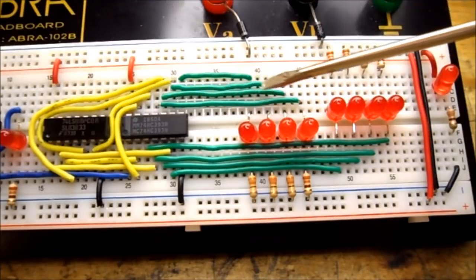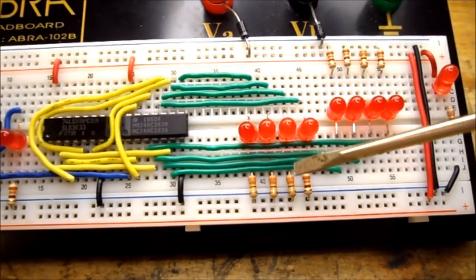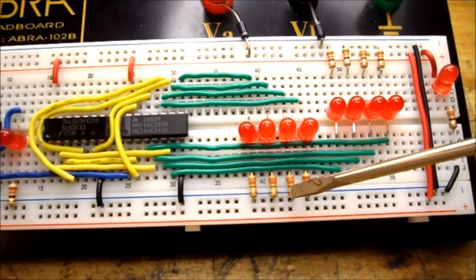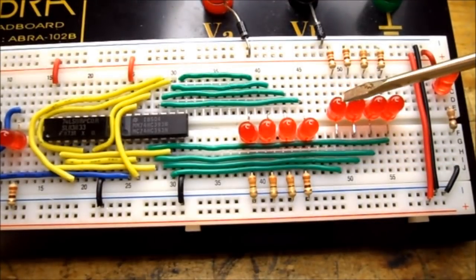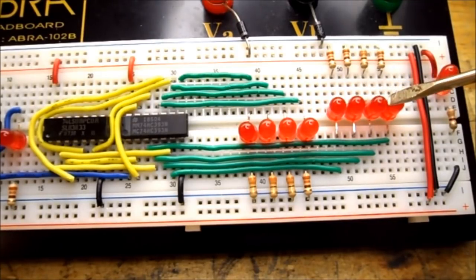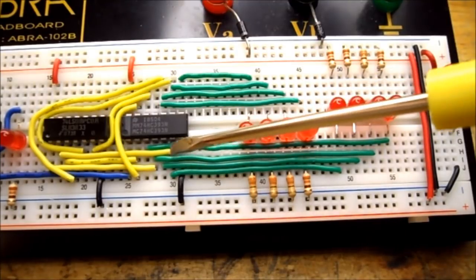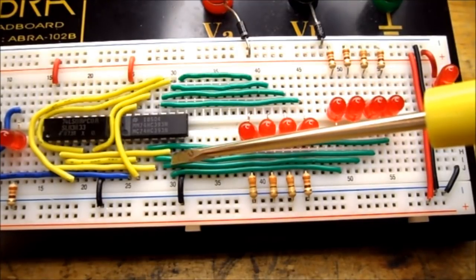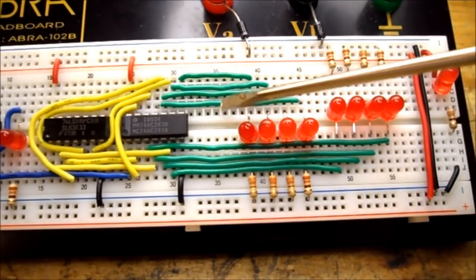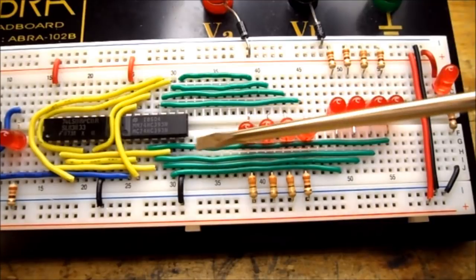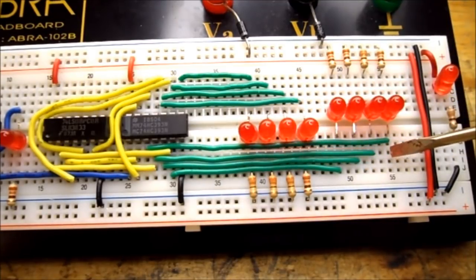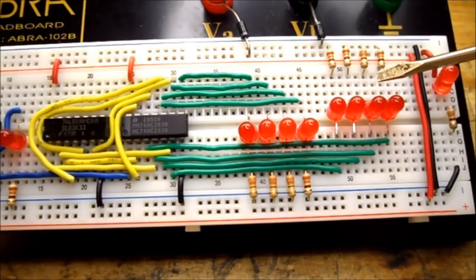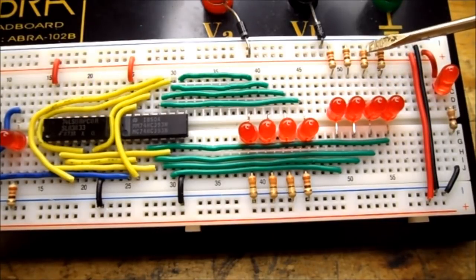So power comes from the IC, goes through the LED, through the current limiting resistor to ground. Now this is my least significant digit. It counts 0 through 9. And you'll notice its outputs on the 393 are on this side of the LEDs. So rather than routing my wires up, around, and over, I decided to route them straight across. So this is the positive side, or the long leg of the LED. The other side is the short leg that goes through the 330 ohms to the ground bus.